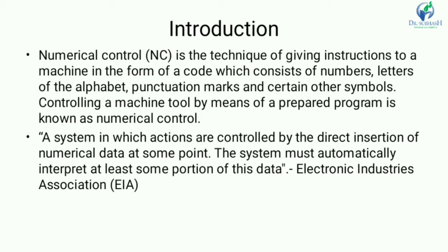The designers of NC machines achieved a major breakthrough during the mid-60s when they could integrate the NC machine tool with a minicomputer. The technology was then renamed computer numerical control. The integration of computers with NC machine tools resulted in a number of advantages like increased memory for part program processing, increased capacity for storing large part programs, easy editing of part programs on the control console, and realization of control logic through software.